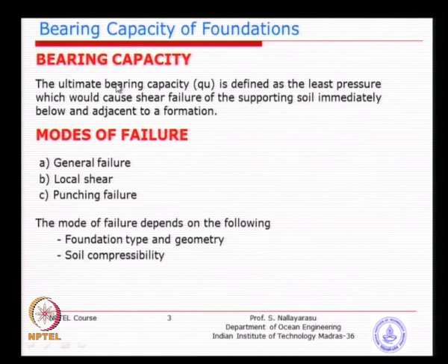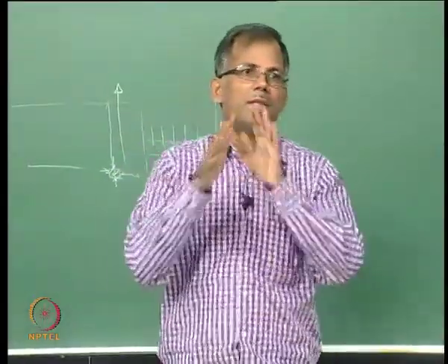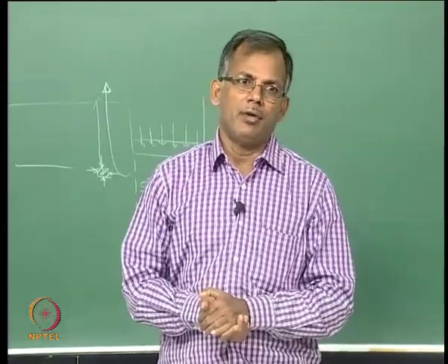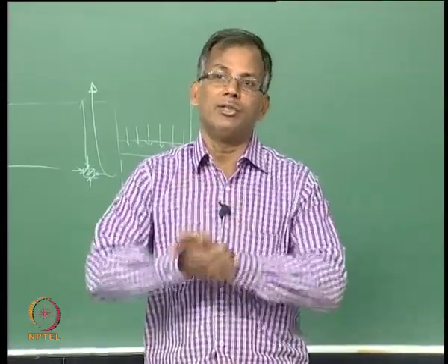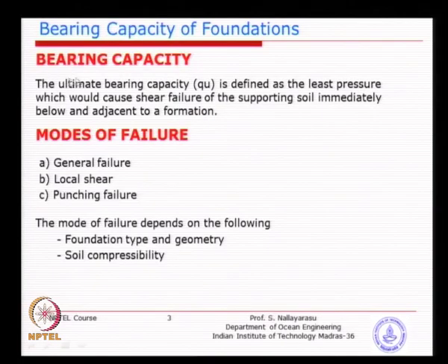So, what we define as ultimate bearing capacity is the least pressure by which the foundation will fail by shear. Basically, if you put the pressure here at this point, when you apply that pressure, the foundation will make the soil fail by shear, and that will be the pressure that we are looking at, called ultimate bearing capacity.